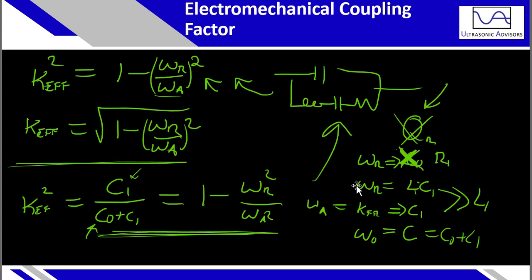So there's multiple ways of going about calculating the equivalent circuit parameters, using a few parameters to measure the others. I would personally not rely on that format. So like, oh, I don't need to measure my anti-resonant frequency because I already did my resonance Q, and as long as you get an equivalent circuit, you can then calculate an anti-resonant frequency. Well, that's true, but it's better to measure, due to sometimes the device not being consistent with linear theory. Surprise, surprise. Not everything in life is linear. And sometimes the deviation is larger, sometimes the deviation is smaller, but that's the way things work.